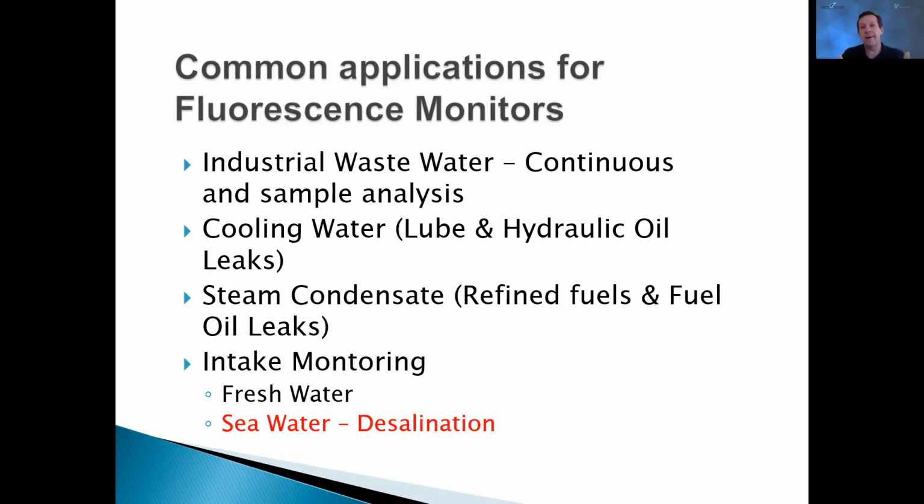For measuring of algae, it's a different scenario. There's always algae present in the water. So the device is always seeing some type of response. It's always giving you some type of indication, but it will definitely trend with the changing of algae concentration in intake waters.